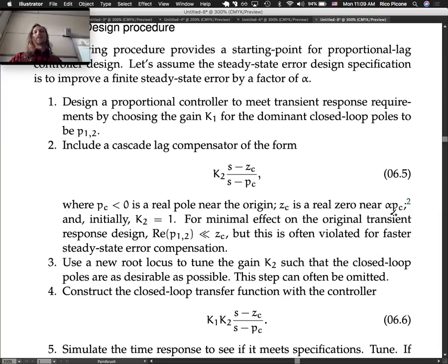You would get maybe a 10% improvement in your placement if you actually calculated what alpha should be, or what the factor here should be. You can do that, and the Nise textbook discusses it, and I used to teach it that way. But I think that it's actually premature optimization. So K2 equals 1 is what we start with. We just say, okay, K2 is equal to 1.